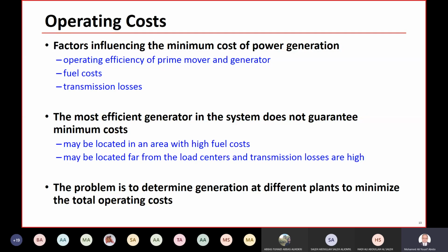Of course, this is the efficiency of the overall plant. I say 50%. Maybe someone asks, the generator efficiency is very high. The generator could be 99% or 98%. But of course, the cost in general is not only the generator but also the turbine and boiler. The overall efficiency of the plant could be very low, by the way, and thermal power plants could be 30%.